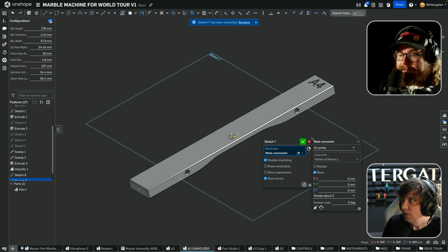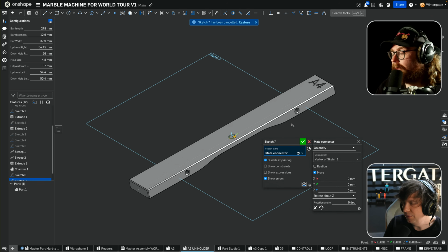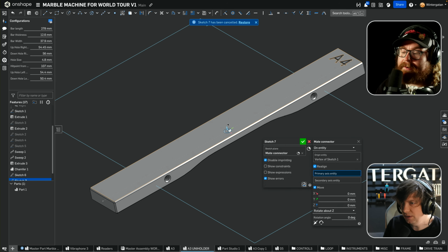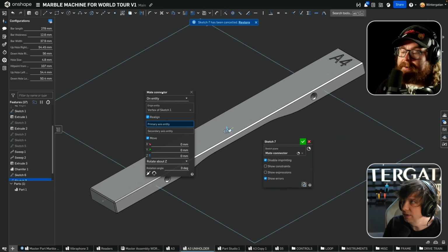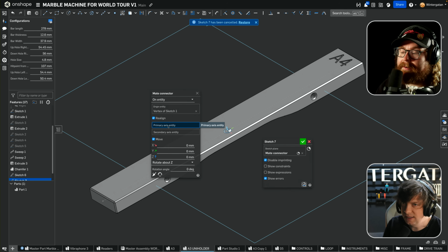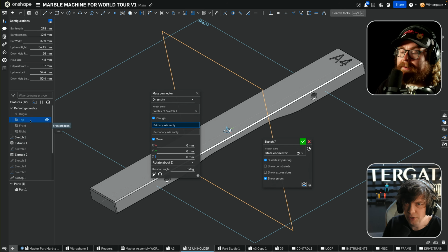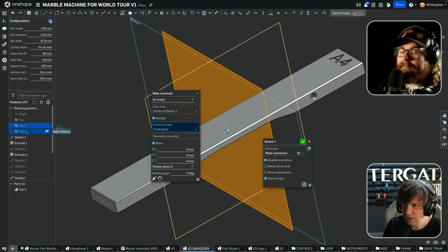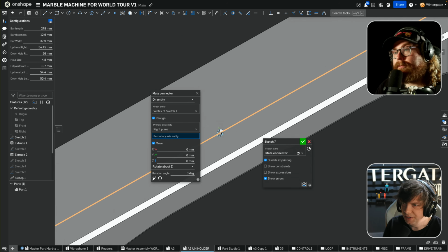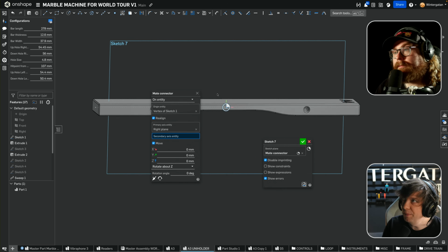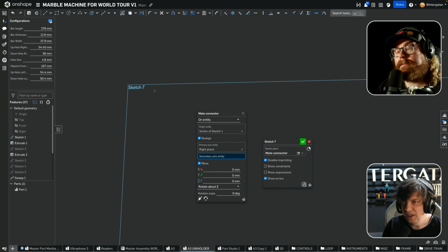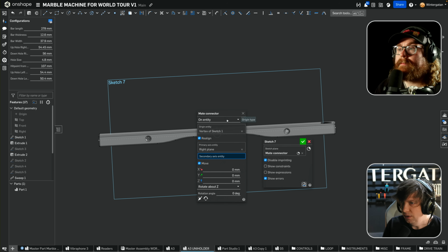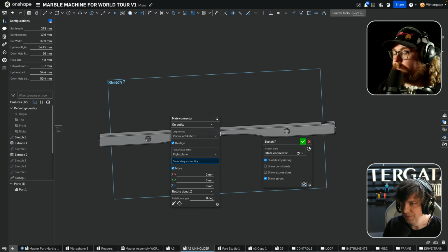Okay. My menu didn't show up because I pressed the wrong place, but now the colors are correct. So we're gonna start this by sketching on a mate connector. And I learned something really great in Onshape. It's that I can set the primary axis using the default geometry. So I can use the front plane. That was the wrong one. I can use the right plane to turn my sketch completely correct. And if you remember this discussion, now this sketch thing is correct. So we're not sketching back and forth and upside down. So we're sketching perfect here on this mate connector.